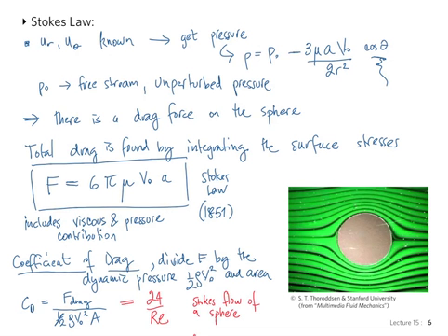Yeah. The pressure and the stress is a function of the U and the viscosity. Yes, I've skipped the tangential stresses, but that's also going to depend on the viscosity. And what's interesting here is that the normal pressure also has a viscosity component. The fluid is so viscous that it pushes on this thing. It doesn't go completely around, like always tangential. So the normal stresses have a viscosity component. This is a strange or different thing.